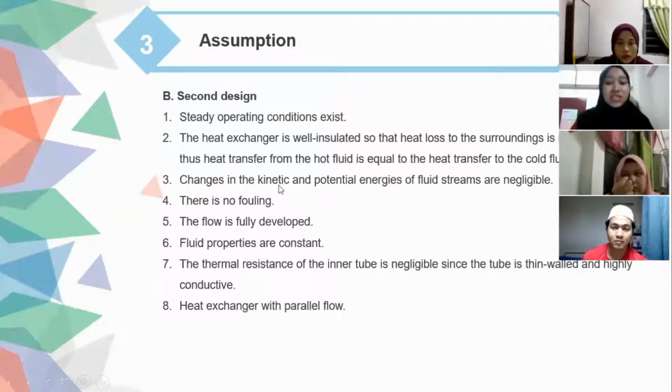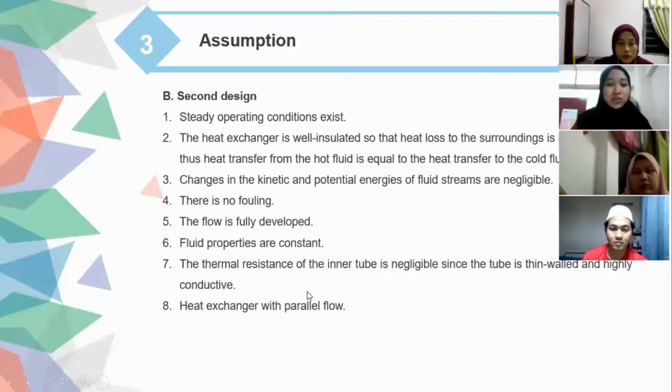Changes in the kinetic and potential energy of fluid streams are negligible. There is no fouling. The flow is fully developed. Fluid properties are constant. The thermal resistance of the inner tube is negligible since the tube is thin wall and highly conductive. And the last assumption is a heat exchanger with parallel flow.